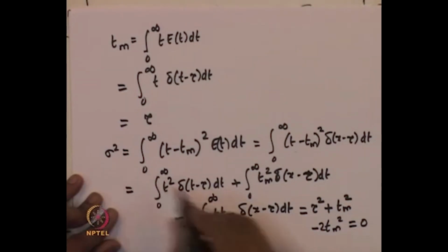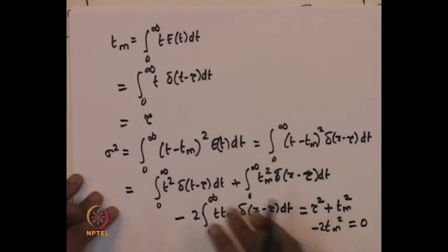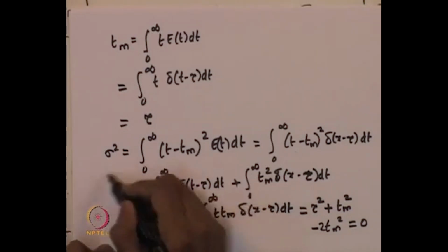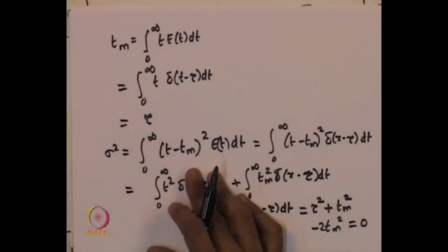So, therefore, the variance is actually equal to 0, and that reflects the property of the RTD function that we intuitively guessed. That is, there has to be a spike at exactly t equal to tau with an area under the curve equal to 1, and the height of the spike is equal to infinity, which means that the variance should be equal to 0 for the distribution.